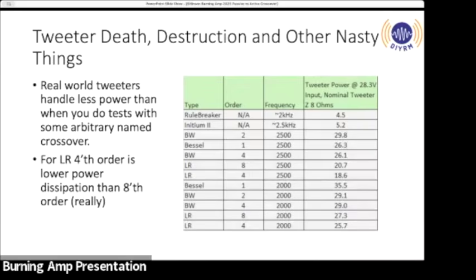So again, if I played at 23.83 volts, nominally 100 watts, and I had an honest-to-God Linkwitz-Riley 4th order electrical crossover, the tweeter with pink noise gets 18.6 watts. It would still burn up. Okay? Here's the kicker. Linkwitz-Riley 8th order crossover, 20.7 watts. Higher order, more power. That's that special case that I was talking about.